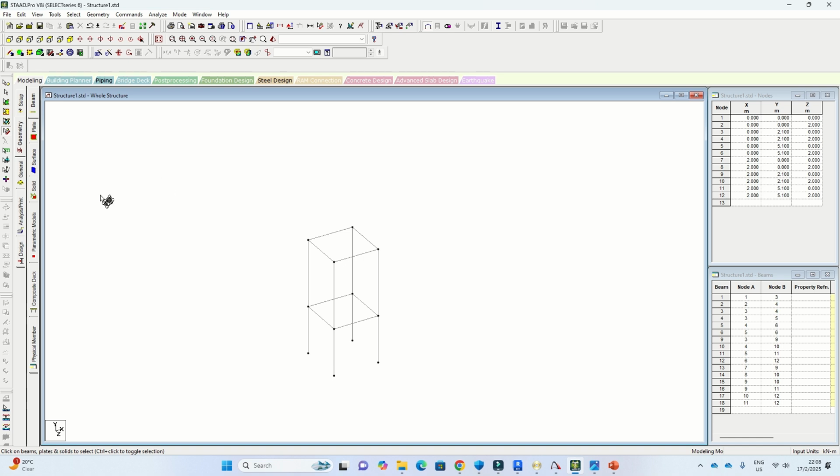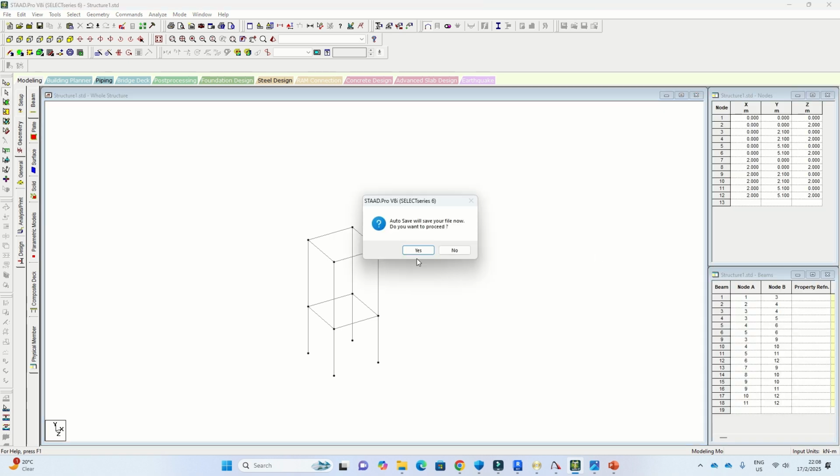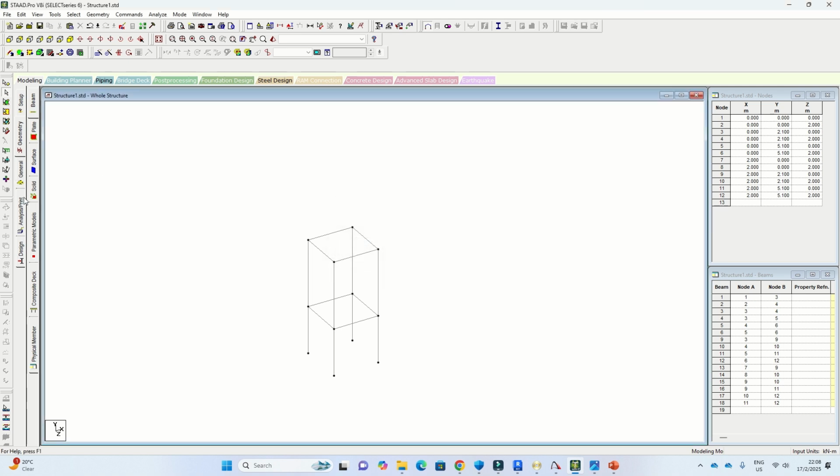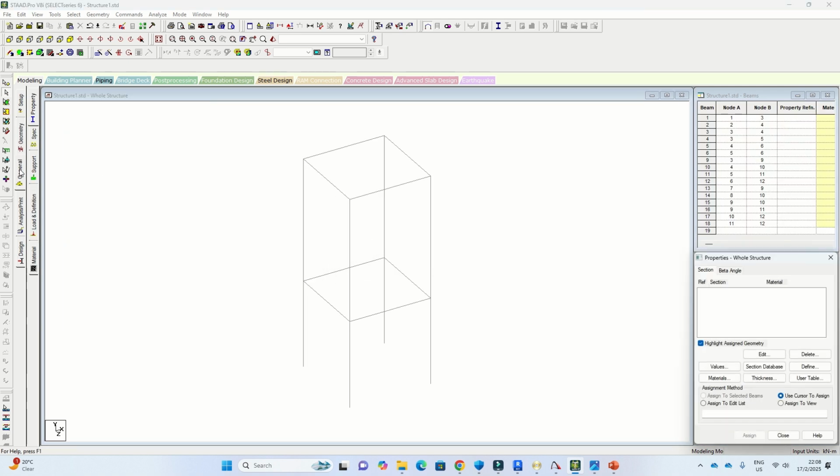Now I'm going to add section properties. The bending effect of this structure is affected by the material used to create the members. In this instance, I'm going to use concrete. So I was at this stage. I'm going to go to geometry, which is where I was, and I made all these things. I'm going to save. Then from there I'm going to general.